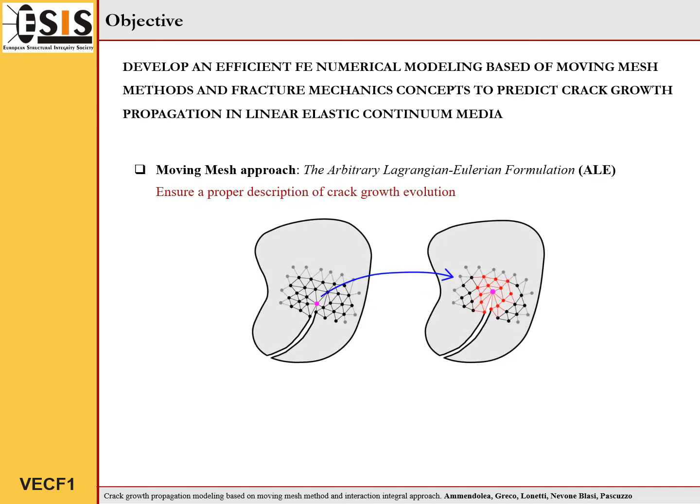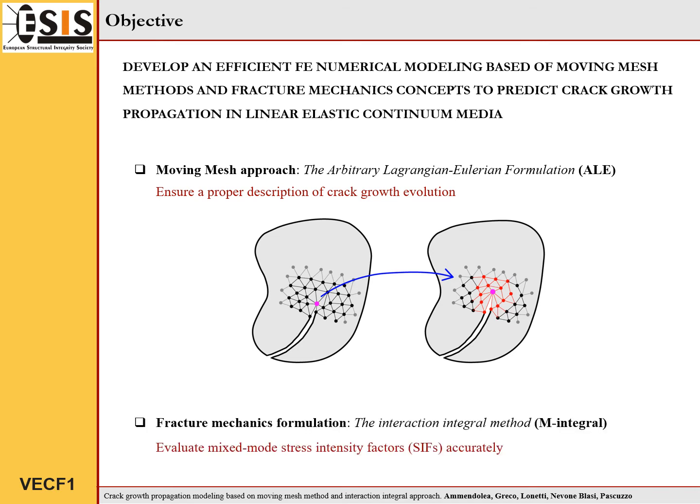The moving mesh method, based on the arbitrary Lagrangian-Eulerian formulation, is adopted to appropriately describe the evolution of discontinuities within the computational domain. The interaction integral method is employed to accurately evaluate the stress intensity factors of the crack problem.